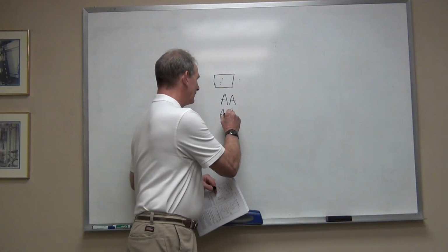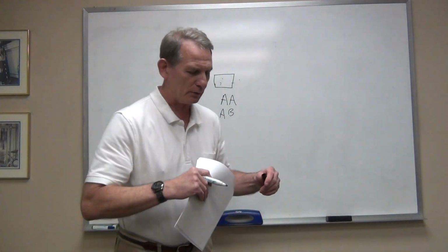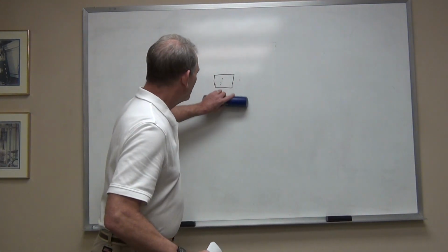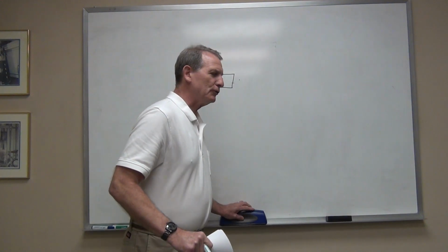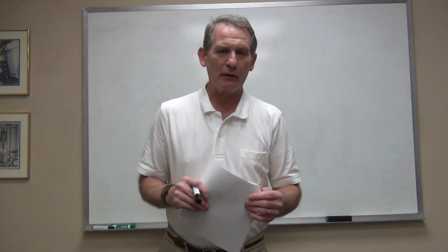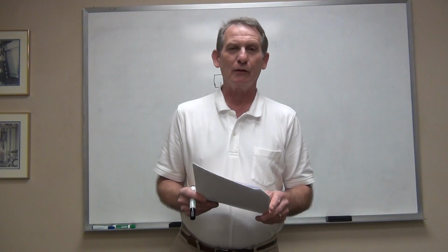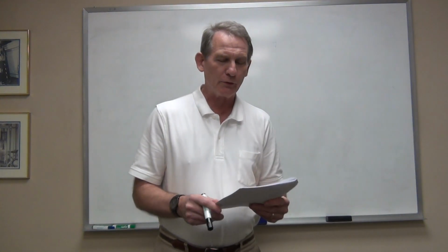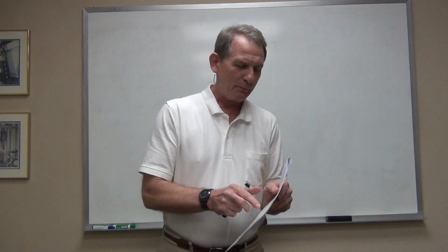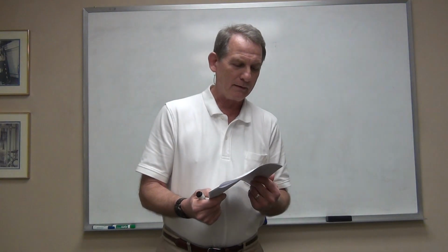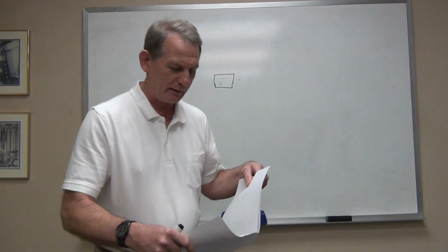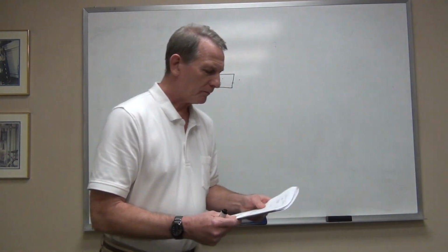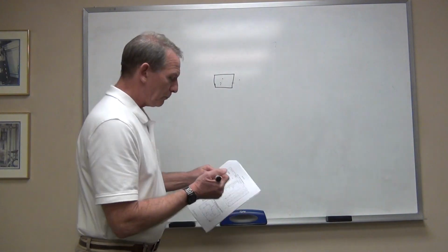A, B, A, C, and so on and so forth. So you basically have an unlimited or a very large number of datums available to you. Again, very seldom are you going to see anything close to even 23 datums on a drawing, but if you do, you might see that double datum notation.